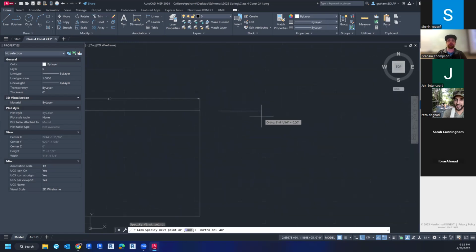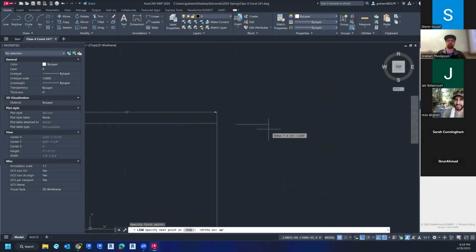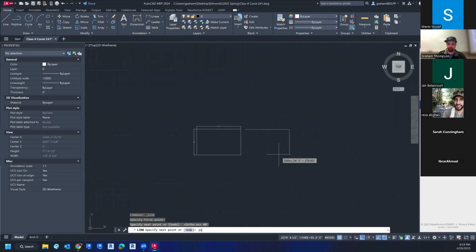it might take it, it might not. But it looked like earlier on another computer, they typed in 40 feet, and when they clicked, it set the dimension to wherever they clicked. So instead of clicking when you type a dimension in, anytime you are in the command line, we want to hit that enter button. That's going to say, hey, I want this to be 40 feet long, enter. And then I want to draw it down 25 feet, enter. So we're not using our mouse. Our mouse is going to try to click elsewhere, whereas the command and an enter is giving it a direction. You gave it a direction, you gave it a length, and you said go.